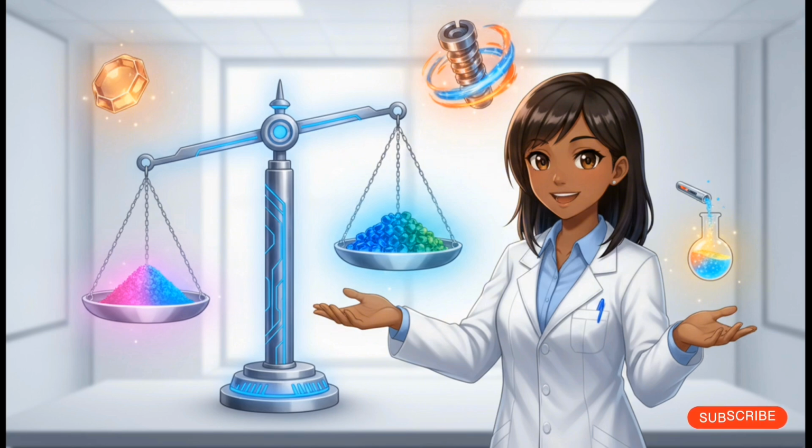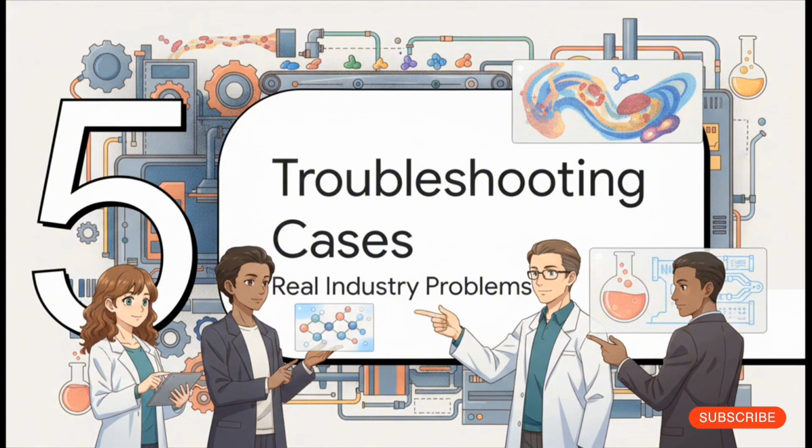Optimizing your pigment loading. There is a golden rule in this industry. Overloading your polymer with pigment will massively, and I mean massively, increase your risk of poor dispersion. You just can't force it. Let's bring all this theory to the floor with Section 5, Industry Troubleshooting Cases.